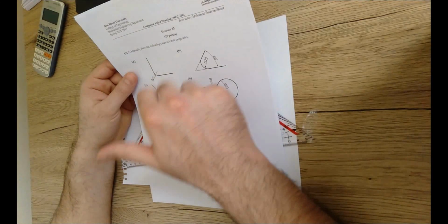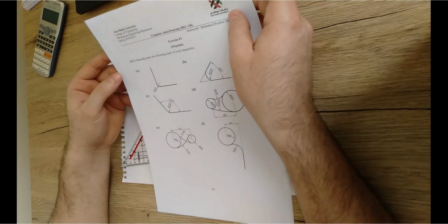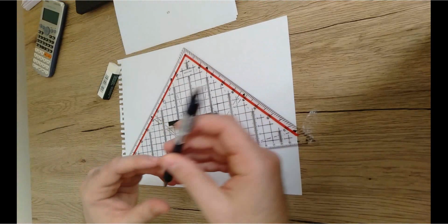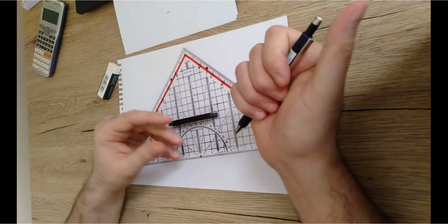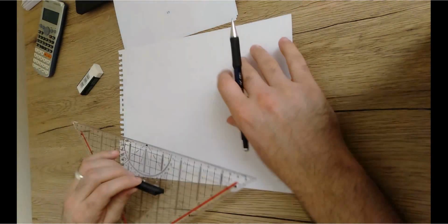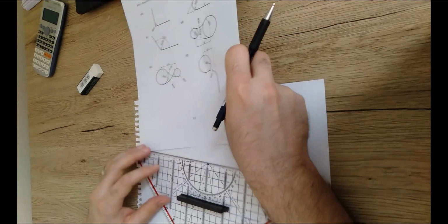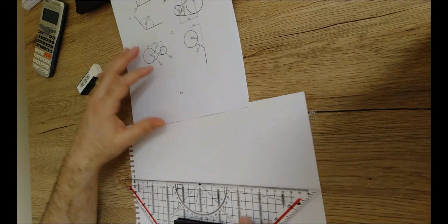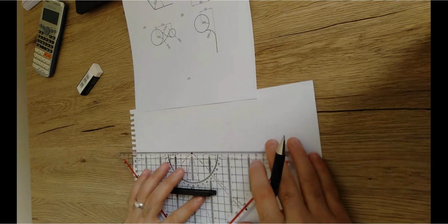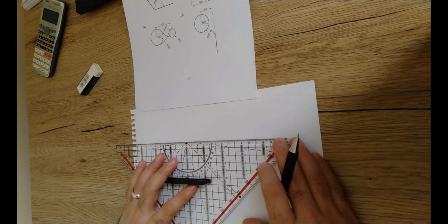The intersection of these two lines is definitely going to give us the center point of the curve, then we can draw the curve as we explained. So I'm going to start with the 0.7 pencil here, and this is my drawing sheet, and I'm going to consider example A in the corner as already given. I'm going to try to make it very similar to what is given here. In the beginning I'm going to draw these two lines here.